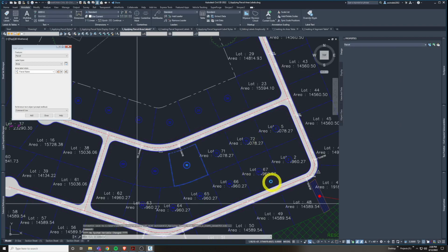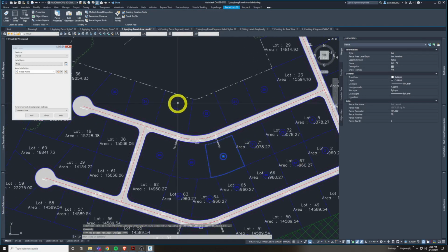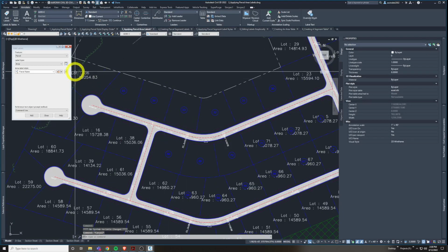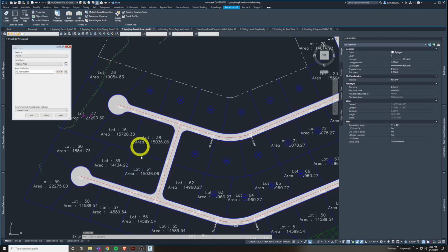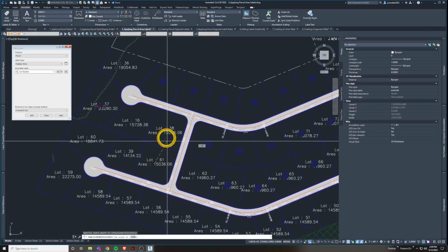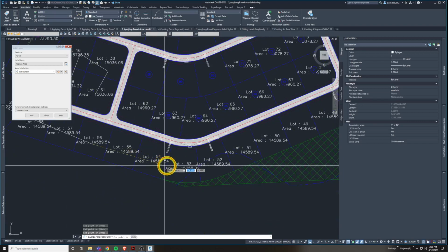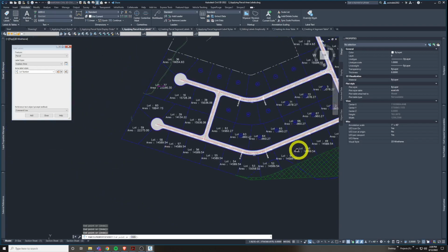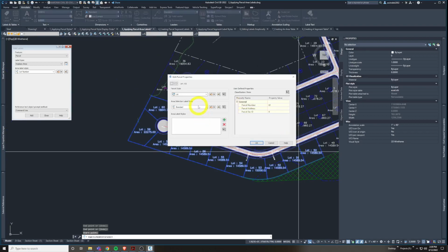We'll say okay. I added a label on top of all of them. Of course, we can just do this one at a time. We can keep replacement area selected. Let's try this again. Let's make a zigzag through a bunch of them. This is a nice graphical additional tool. Hit OK or enter a second time. Let me change these all to lot number. Add.